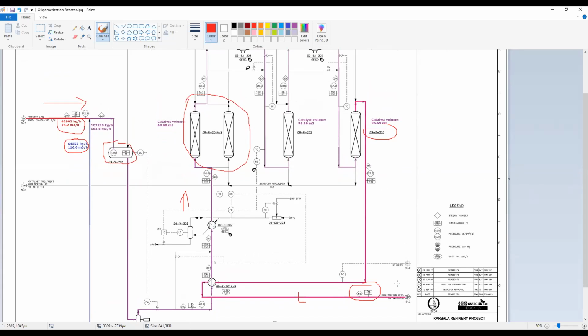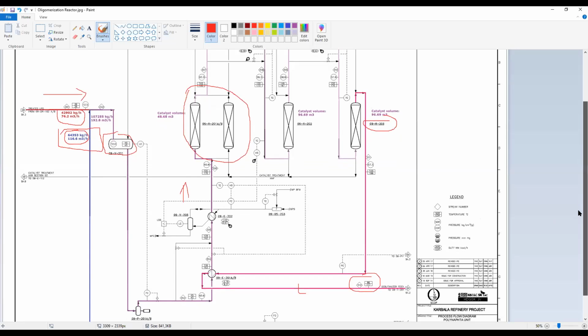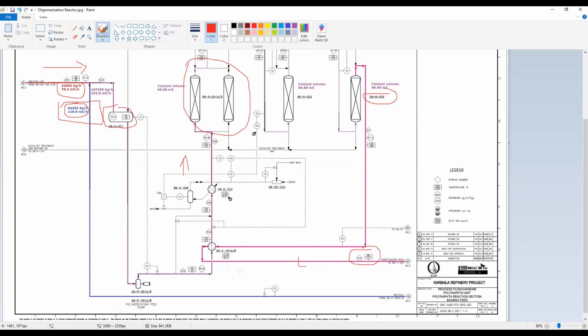So remember the important things, of course, are to keep the appropriate temperature and to keep the recycle with the feedstock. You will combine the feedstock with the recycle, which is a paraffinic stream coming from the debutanizer.